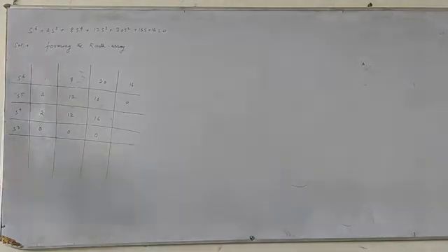Now this is called a row of 0. The row becomes prematurely 0. You should always remember that in any Routh table, a row of 0 will always be on an odd power row. This can never be on an even power row. You take any Routh table, this is a universal truth. Note it down, because this point will be required while we are solving numericals. So it becomes prematurely 0.